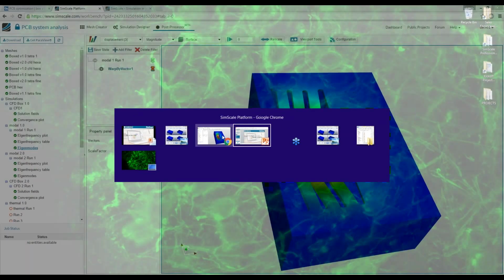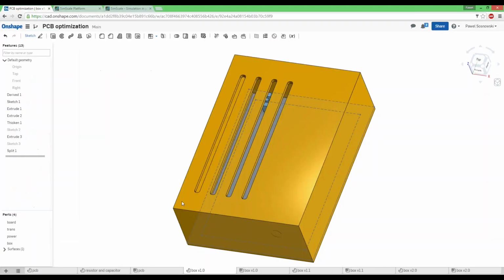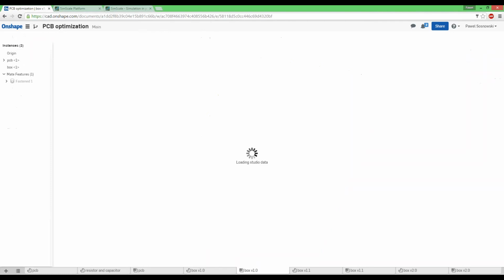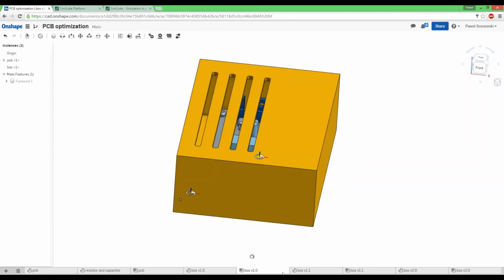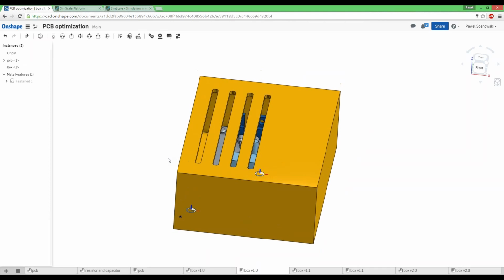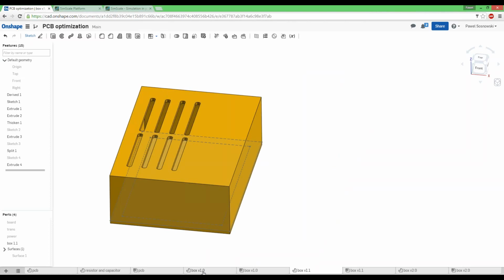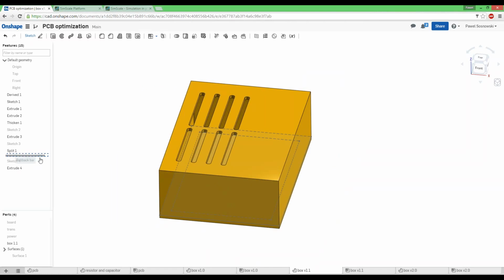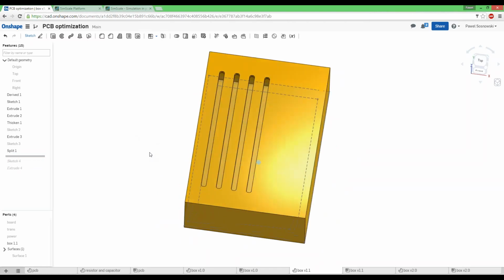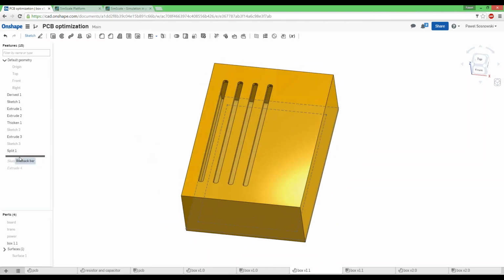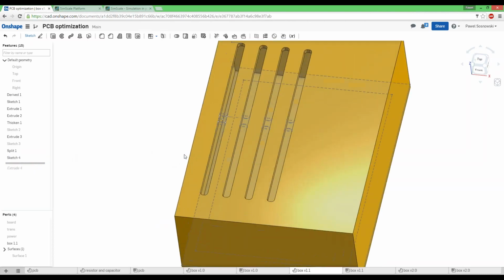Now I just have to select the proper window, which obviously is not always easy. So we had the assembly itself, which was done earlier. Now we just make a copy of our part studio, box V1.0, and perform modifications. You already see what I've done, and I'm sure that you already anticipated the little change that I decided to do. With Onshape it is as easy as adding a sketch to my design.